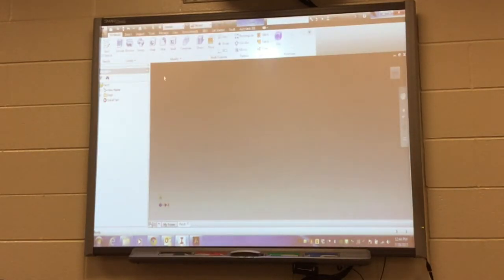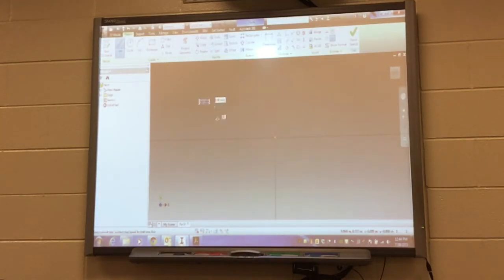That opens up your screen. I'm going to hit create a sketch. And remember, everything we're going to do right now is on the XY plane. So I'm going to go ahead and click the XY plane, and that's going to give us our workspace. I want to work a little bit with the L right now. So I'm going to go ahead and draw my lines in my L. And I'm going to go ahead and make a mistake happen where I don't close that gap in.